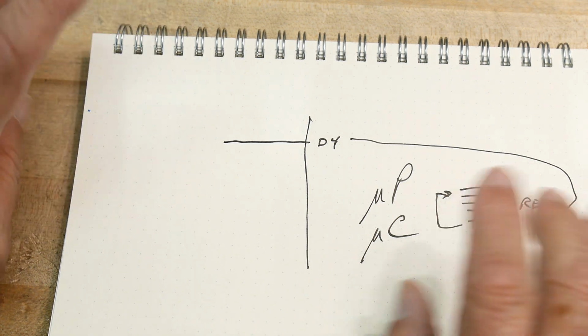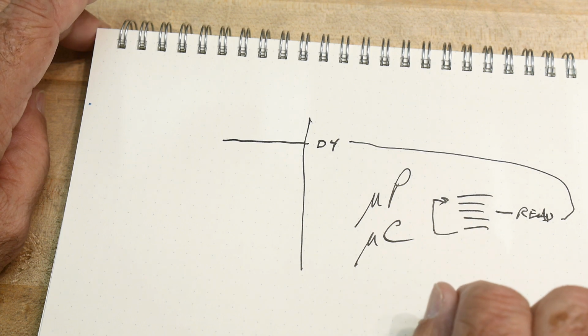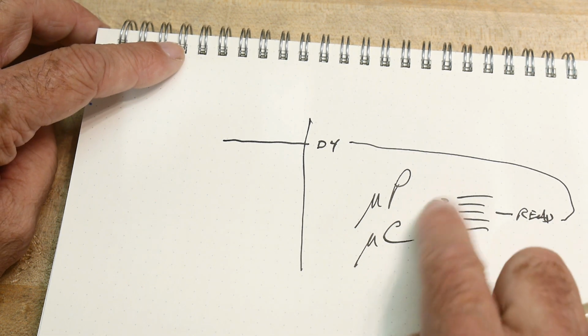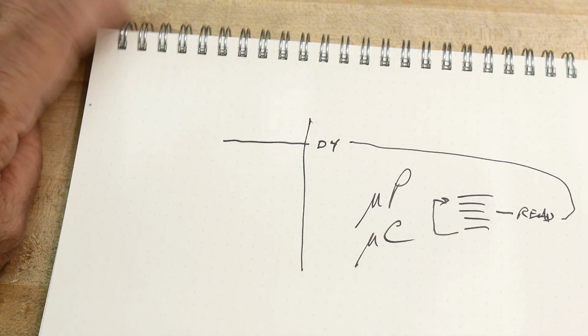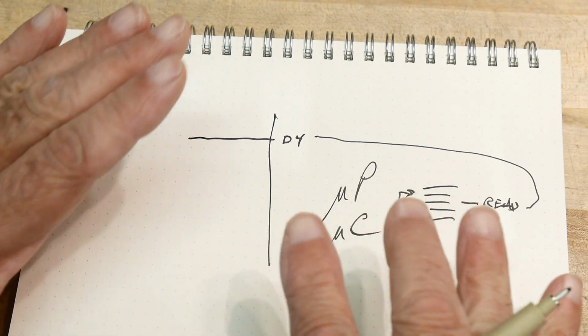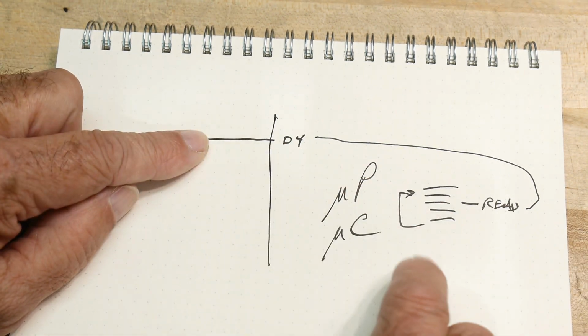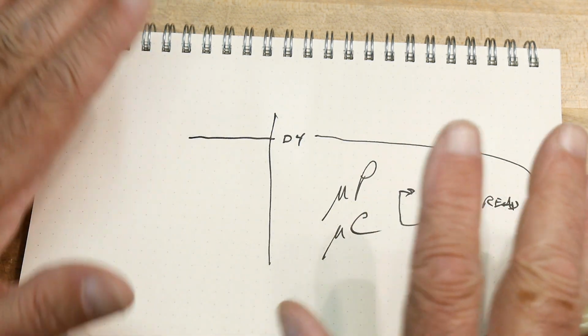This is called a round robin or polling. You'll hear it called different names, but it's basically just going around and around, waiting for this line to go high. Now, people would say this is not edge triggered, this is level triggered. It's whenever the level of D4 changes that the microprocessor finally sees it. So this is a level thing.